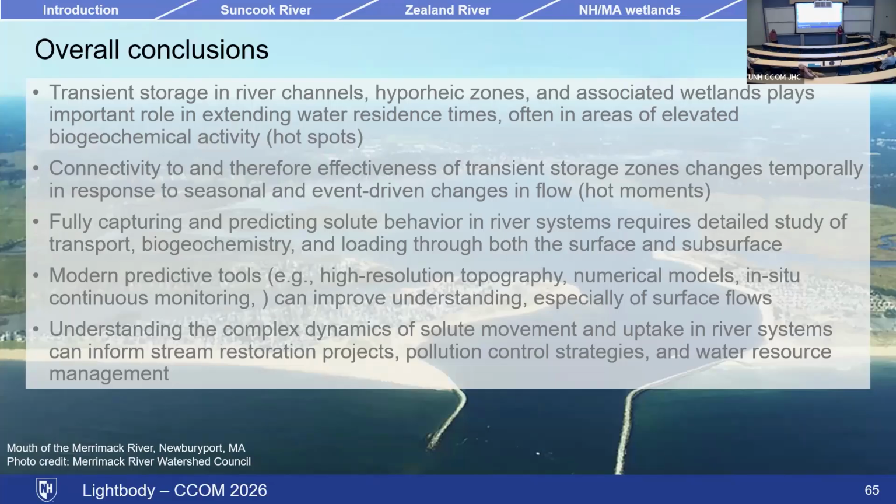We did not do a sensitivity analysis to it. We assumed it's a sand bed river, and so we just sieved 1 or 2 samples, got a median grain size, and then just applied it spatially.